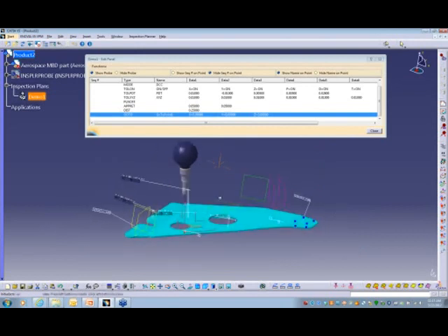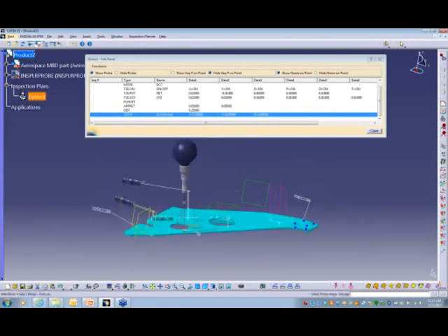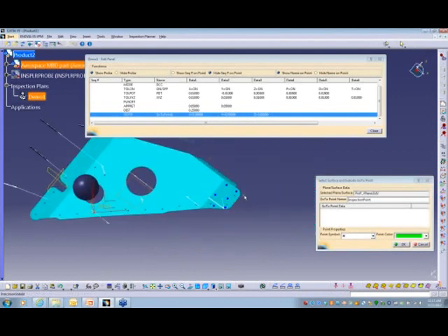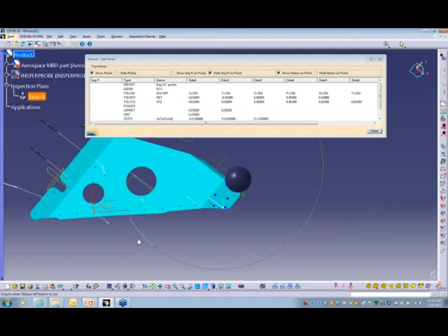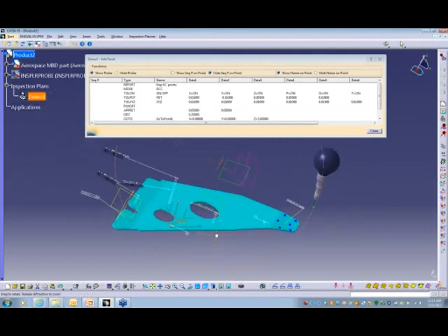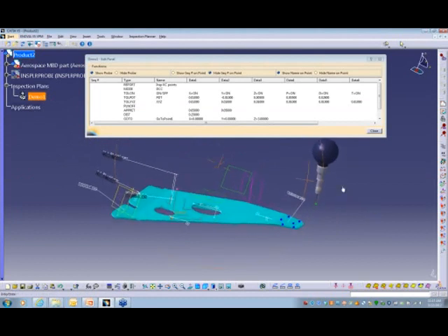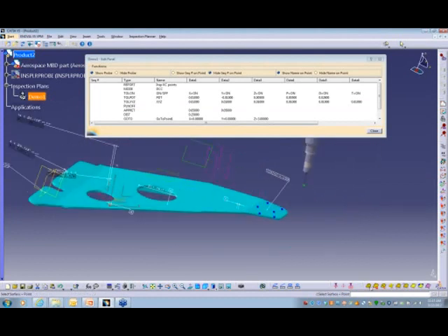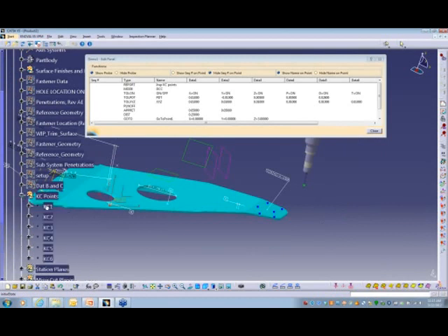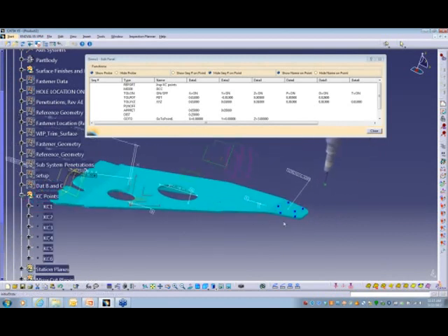And we will come over and we'll actually do a go-to move. One of the real powers of this is we're working inside CATIA. We get to take the benefit of planes and information in the model. So we just indicated a go-to move on a plane inside CATIA, and we will inspect these points that were supplied by the OEM, and they were called key characteristic points.